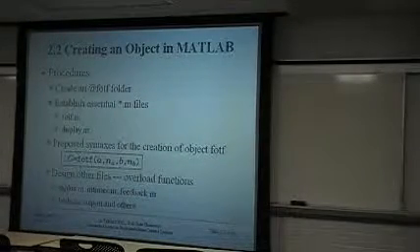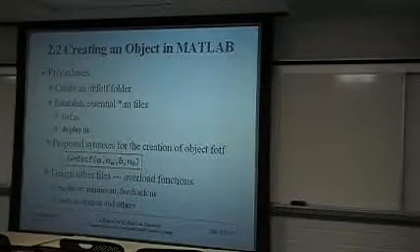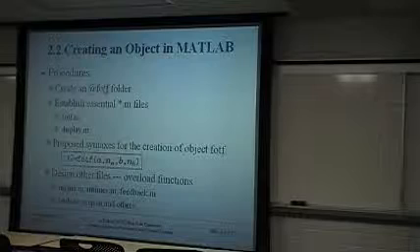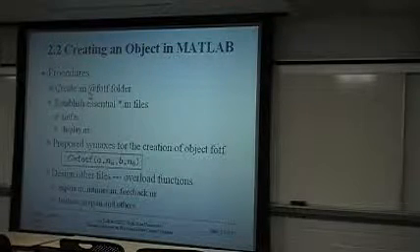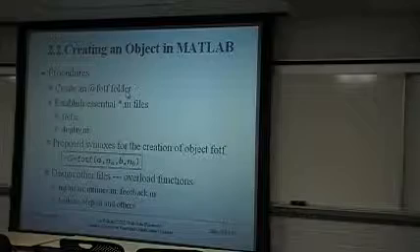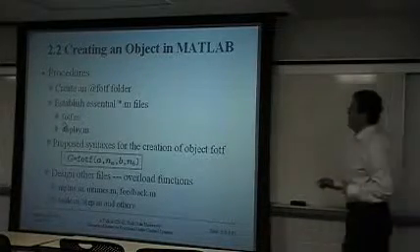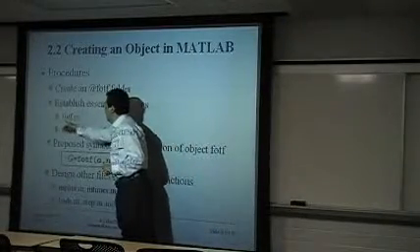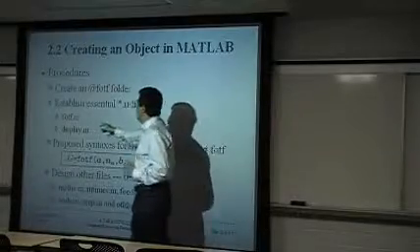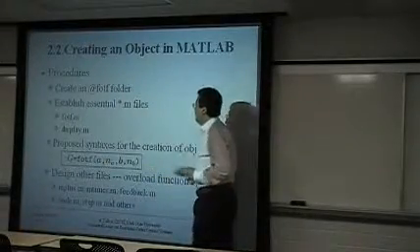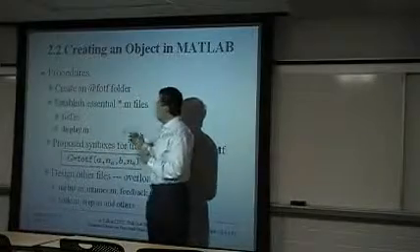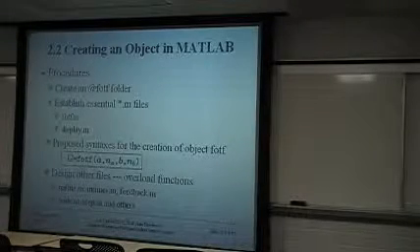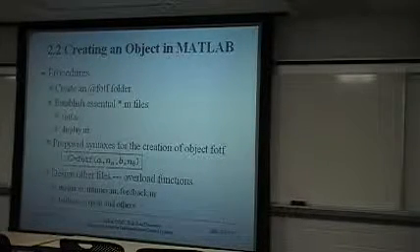And to define an object in Matlab, what we need to do is to create a folder first. The folder must start with @FOTF. And in this folder, we must at least establish two files. One is the definition of this class, which is given FOTF.m. You must write this name, you cannot use other names. The other one is display.m, which is used to display a fractional order transfer function. So those are the essential files you must create in that folder.